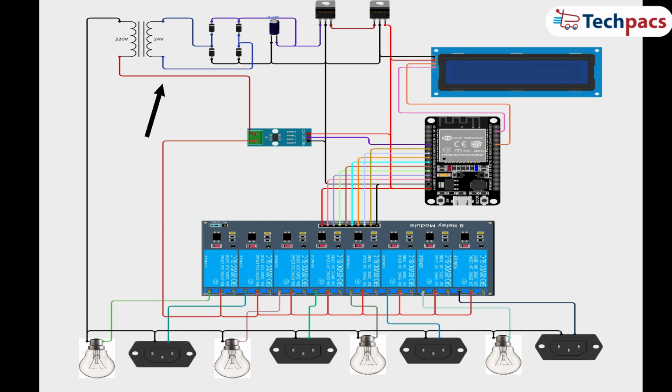Power supply, 5-volt 20A SMPS. The SMPS is used to provide the necessary power for the relays and other components. It ensures a stable 5-volt DC output capable of supplying up to 20 amps, which is sufficient for driving the entire circuit, including all 8 relays.